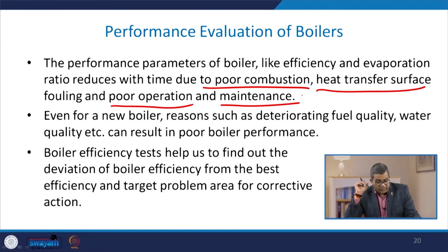Even for a new boiler, deteriorating fuel quality and water quality are again very important reasons. If you have water with a high level of turbidity, high level of total dissolved solids, TDS, or high level of hardness, all of these can contribute to poor boiler performance.